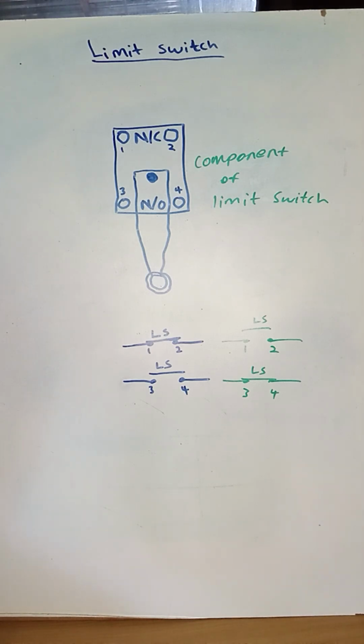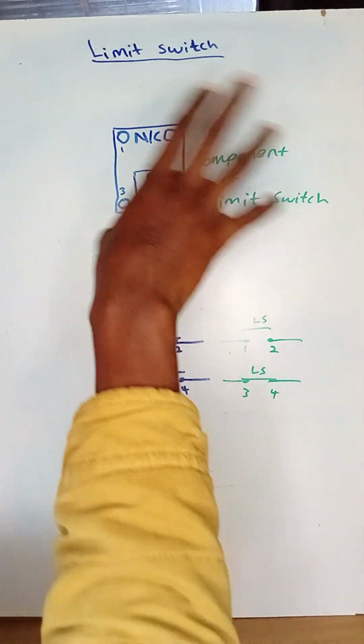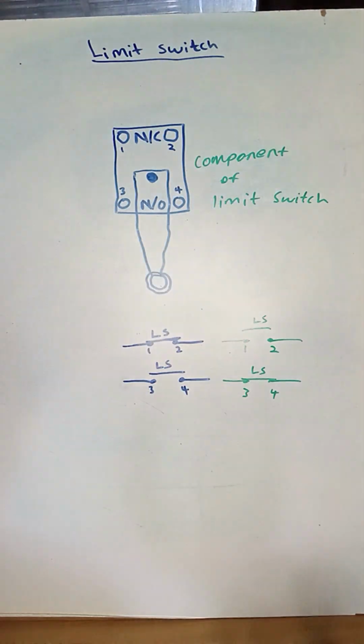The limit switch doesn't use a coil. As you can see, there's no A1 or A2 here. It's just its auxiliary contacts. So right now you know how the component of the limit switch operates, and also how it affects its auxiliary contacts. Now I'll draw the wiring of the oscillating panel forward or reverse in the control circuit, but I'll only draw its components and its auxiliary contacts.